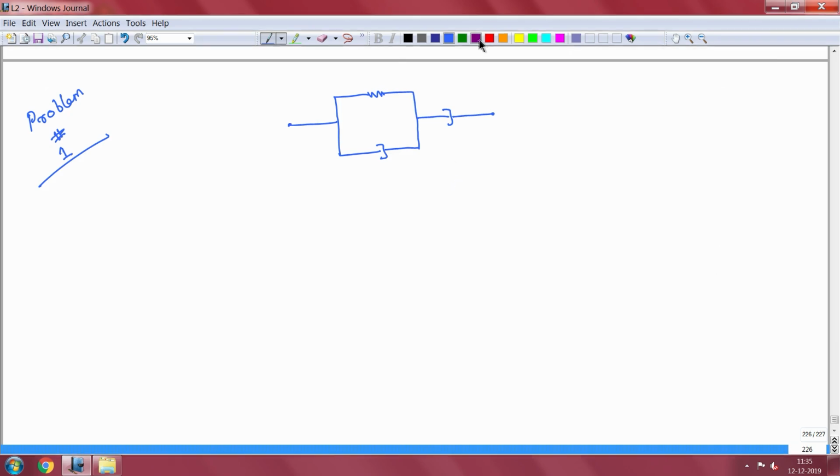And what we are given are the values for the moduli that we will use. Here the spring is characterized by E, which is given as, let us say, 300 pascals. The viscosity here is given as 5, and this is another viscosity, given as 1 pascal-second. So we see that we have these two different dashpots, and the strengths of these dashpots are different.